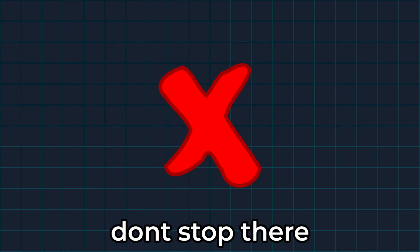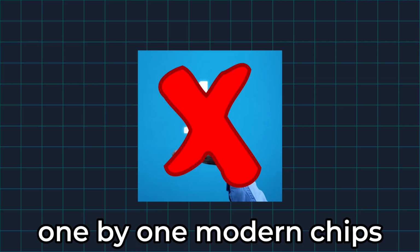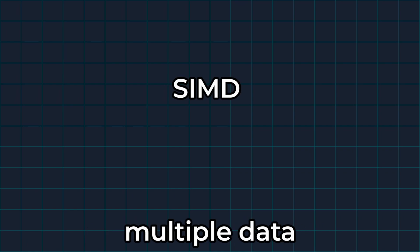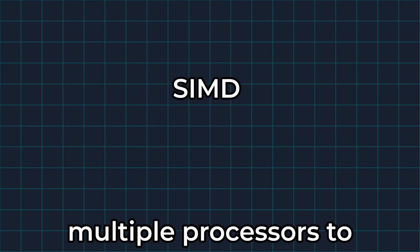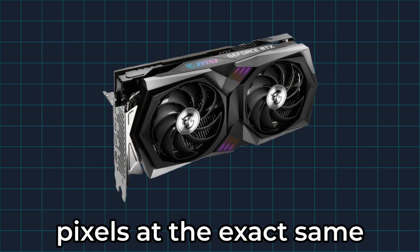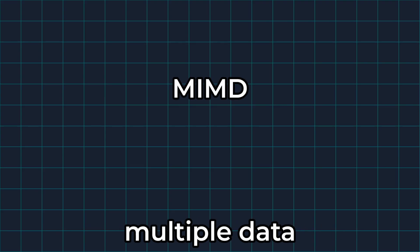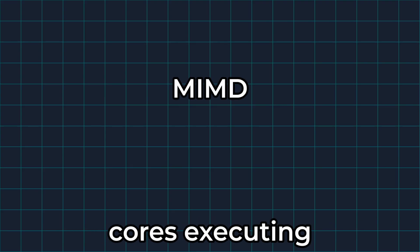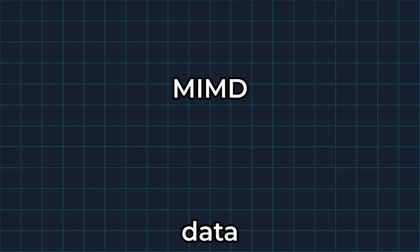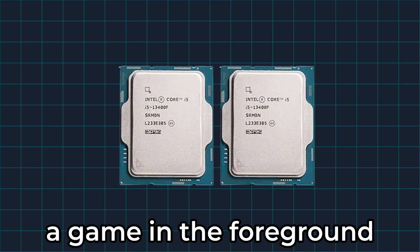But contemporary chips don't stop there. To push speeds even further, they use two major techniques. Instead of doing tasks one by one, modern chips do them all at once. SIMD, or single instruction multiple data: one command is sent to multiple processors to work on different data. Think of a GPU changing the brightness of millions of pixels at the exact same time. Then we have MIMD, or multiple instruction multiple data: multiple independent cores executing completely different instructions on different data. This is your multi-core CPU running a video render in the background while you play a game in the foreground.